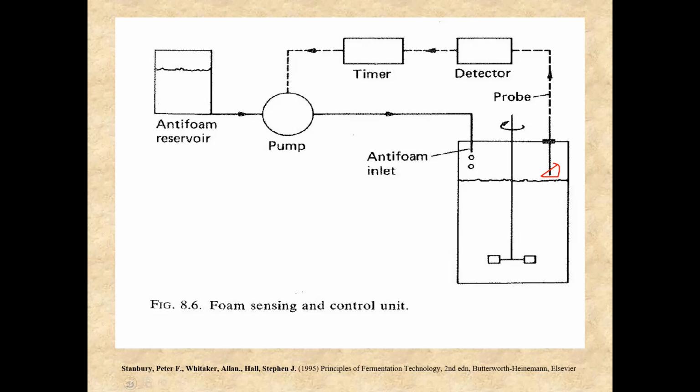So you can see here, this probe is set above the broth surface. It is not touching the broth directly, not coming into contact with the broth, and it is above the broth. It's not immersed into the broth. So when the foaming occurs, obviously the foam will rise, and it touches the tip of this probe. Now the tip of the probe, remember, is not insulated.